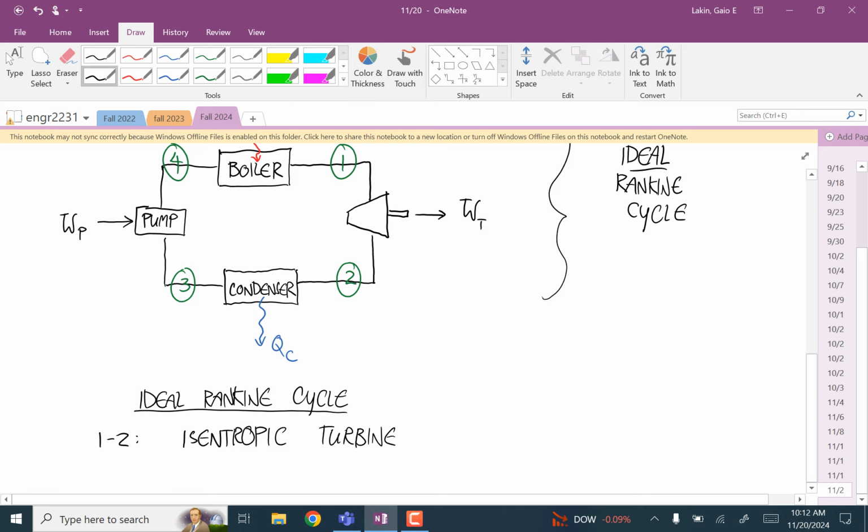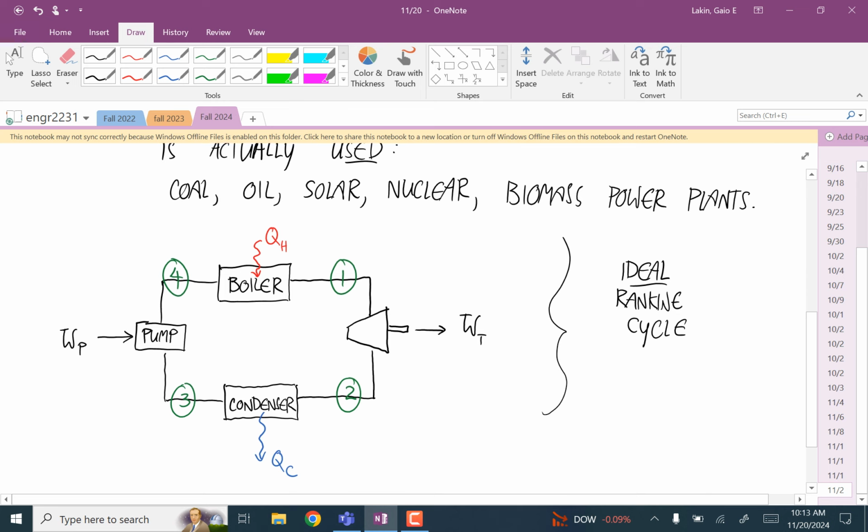Who remembers what isentropic requires? Two things. It does mean constant entropy. And then, it's hard to visualize entropy, but what things can we visualize? Well, this is a turbine, so there's definitely work. It requires no heat transfer and internally reversible. Of course, we're assuming internally reversible. I've already said that like 5 times.